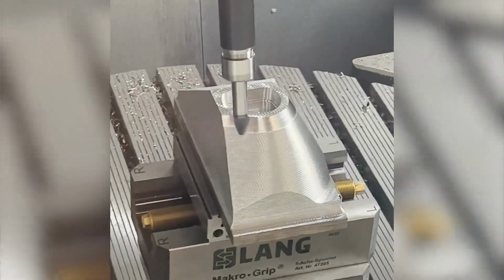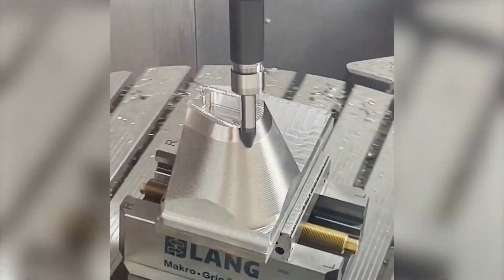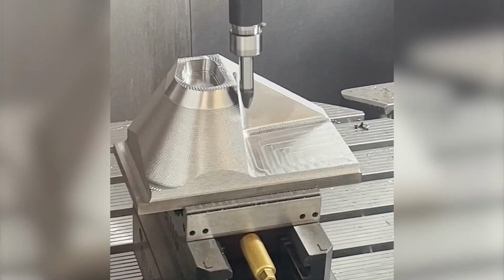By leveraging the larger contact radius of this taper barrel cutter, we were able to maximize the step over, resulting in a significantly shorter tool path. The reduction in machining cycle time amounted to an impressive 70%. Also, the surface finish was superior compared to using a ball end tool. Great job, Ashish. Your demonstration of the new milling capabilities was truly impressive.